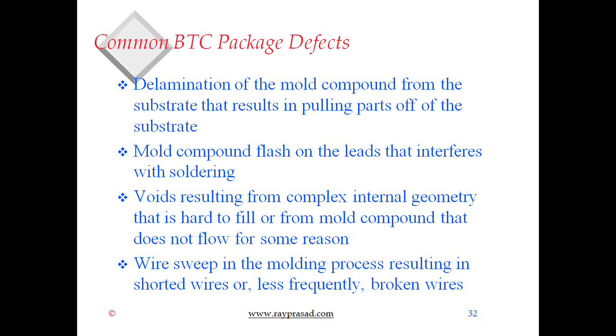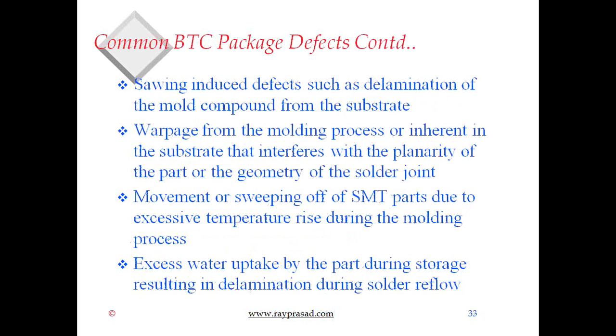And there's all this wire bond inside, and if the temperature and process are not properly controlled, it could make those wire bonds inside move, what they call the wire sweep, and they will short inside, and they sometimes might even have wires that are broken. Those are the things that package guys have to inspect and make sure that you don't get it.